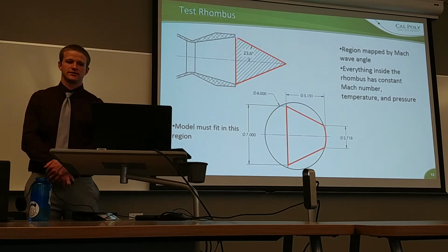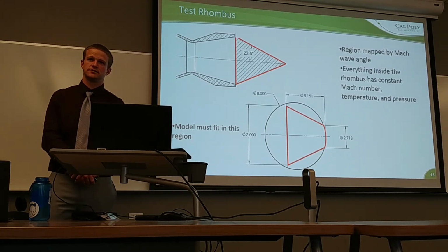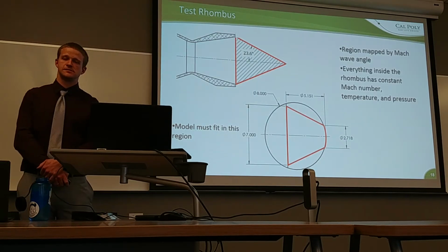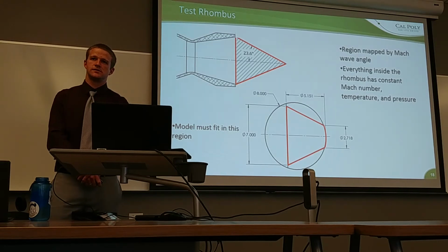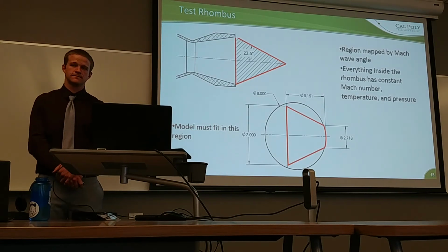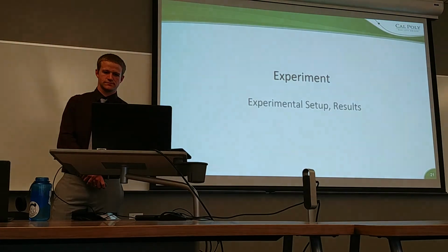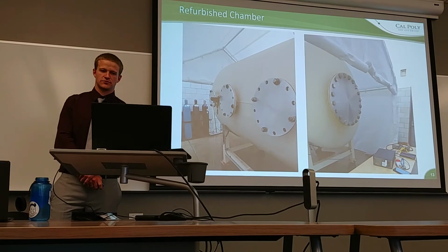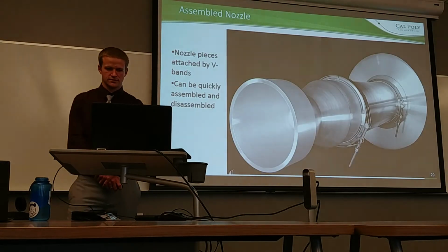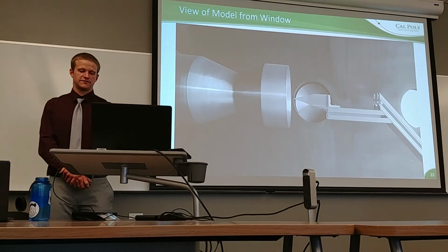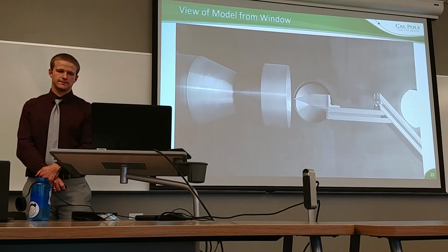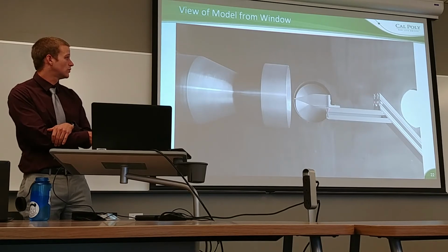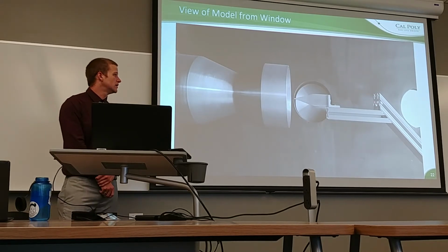I was a bit concerned about the sting itself. I know you said you just put it together and did not give a lot of time to it. It looked really blunt to me, really close to the model. Do you think there's any communication between the front end of that sting? There's certainly going to be, it's so blunt, there's going to be a normal shock that's going to establish. Definitely, especially at the base of it, right here. Yes, that's a good point.